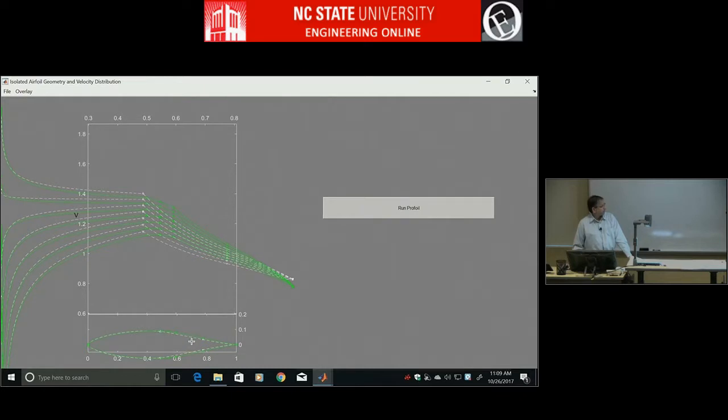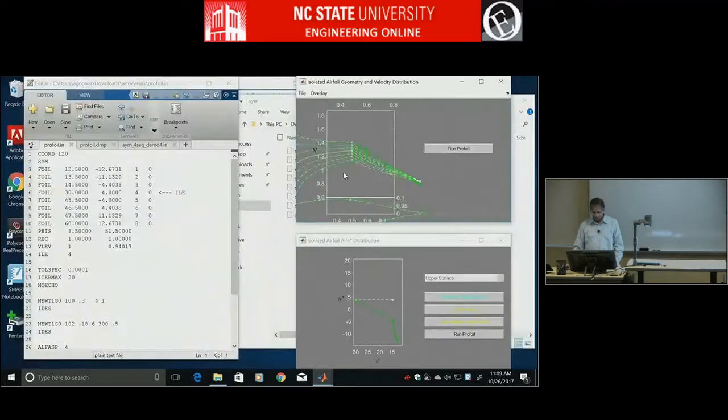And you know, that would be so hard to think about with just looking at airfoil geometry. I mean, maybe with some experience you can say this airfoil is not going to be so good, this will be better. But I think velocity distributions is a more natural step towards how the airfoil is going to perform. Well, what the heck, let's go run this in X-foil. If I get caught up and it takes too much time, I'll abort. But so right now the latest one is demo 6, right?